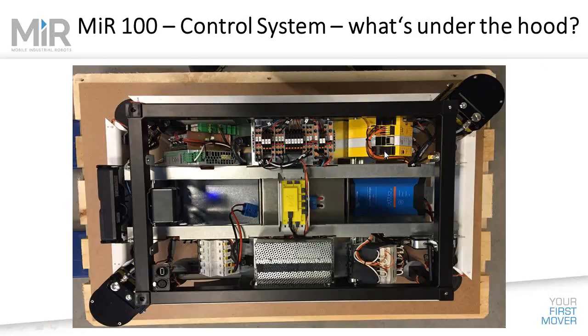And if someone comes into its positional alarm point, it will stop the robot via these force-guided contacts here. So you've got force-guided contacts that are being monitored, the PLC, and those all act together in concert as a safety system.